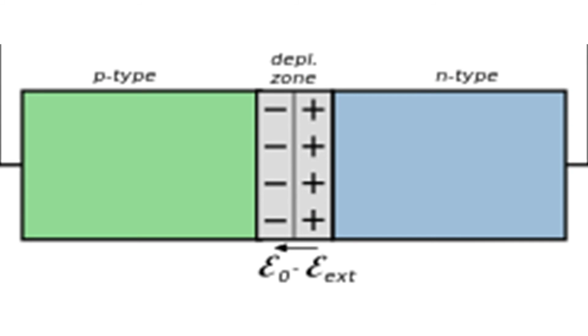Normally, this region only expands so far because the depleted region is dielectric, like electrical insulators tend to be. The more the depleted region expands, the more the electrical potential between the P and N junction across the depleted region lessens, and at the same time, there are fewer positive and negative charges.